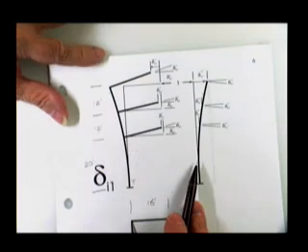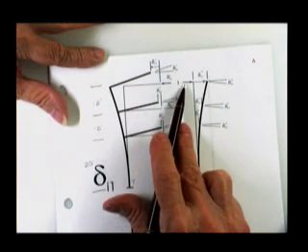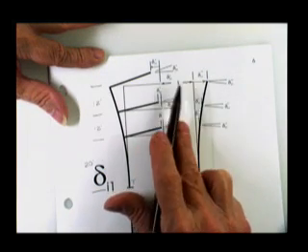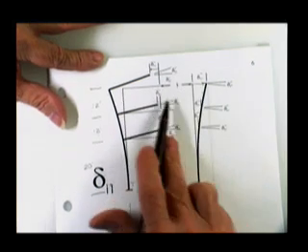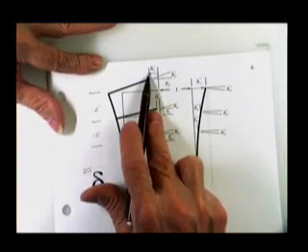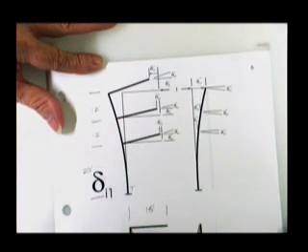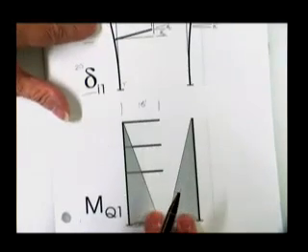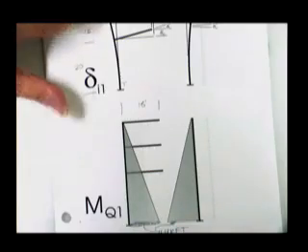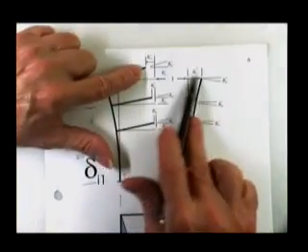Same primary structure. Put a unit load only at this one location in the number 1 direction. Causes a deflection to the left and a deflection to the right. In other words, once you integrate all of the moments with all of the moments dx over EI, you'll get the sum of these two numbers.